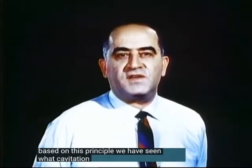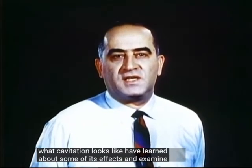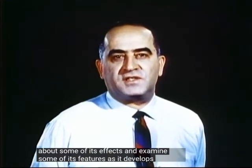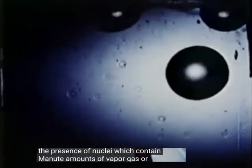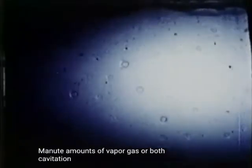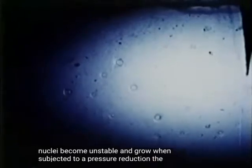We have seen what cavitation looks like, have learned about some of its effects, and examined some of its features as it develops. But how does cavitation, or ordinary boiling for that matter, actually begin? Inception of cavitation in a multi-component liquid at pressures near the vapor pressure requires the presence of nuclei, which contain minute amounts of vapor, gas, or both. Cavitation will occur only when these nuclei become unstable and grow when subjected to a pressure reduction.